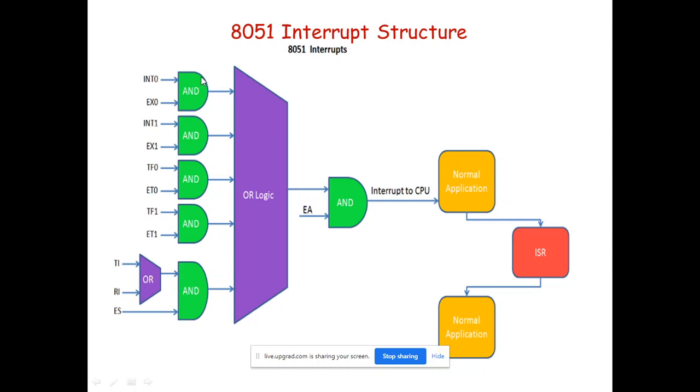Okay. Now according to that, just see this figure. In this figure, there are AND gates. One is for interrupt source INT 0, that is the interrupt coming from the external peripheral, and that is ANDed with the enable external source. Suppose this is 1 and this interrupt arises, that time only this AND gate is on and proceeds to the next.